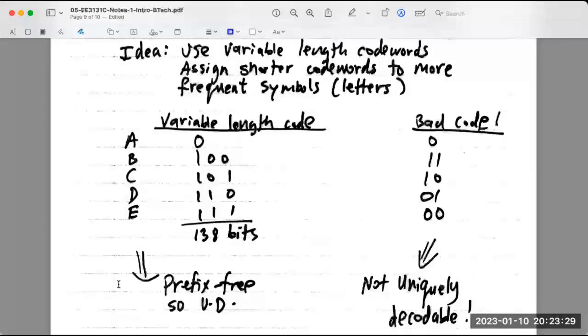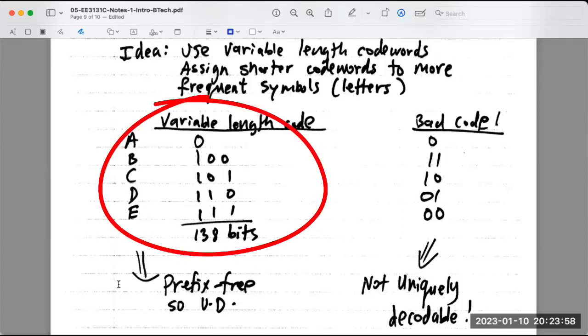So now the rest I did like this. Now you notice that for the rest, I had to start that with a 1, because if you start with a 0, you won't know. Like if this was 000, you don't know if this is 3 A's or a B, right? Anyway, when we talk about source coding, we'll talk about designing codes. But my point here is I represented that file with fewer bits. This is data compression. This is source coding.